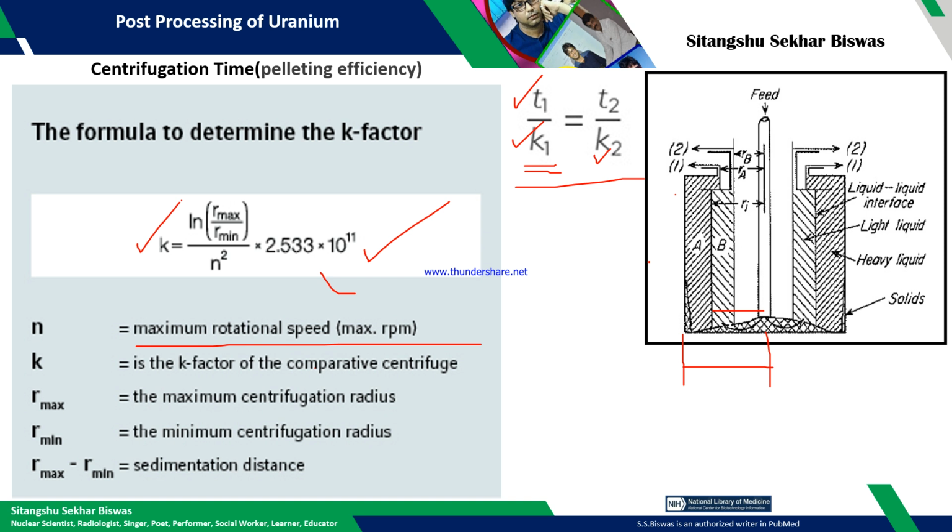You have to use the highest grade of dynamic balancing. Otherwise, any residual mass in the rotor dynamics can cause unwanted vibration. Your critical frequency of rotation. So many technical things are there which are to be considered.